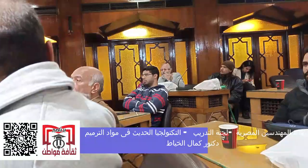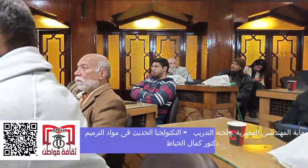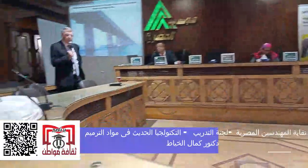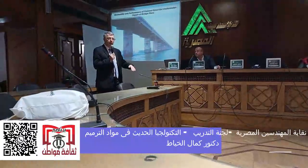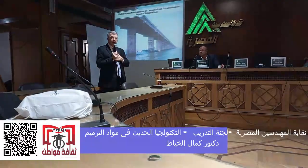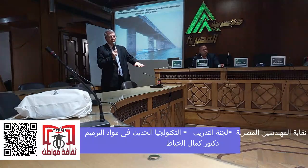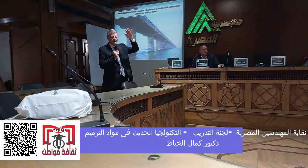Would that be a strategy? Yeah, you're right. Normally, if you look at marine structure, the tidal zone, where you have up and down and splash, that's the one that has the most damage because of wetting and drying and corrosion. So this is where you need the most protection. Submerged zone is less important, and the atmospheric zone.